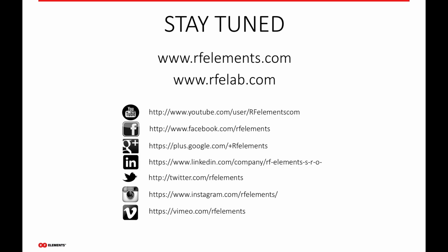Okay, thank you. Another question that just came in is, what makes horns better? Is it the waveguide? Yeah, it's everything, right? And there's no just horn antenna, right? I mean, horn is a very, very generic term to describe what we've created, and what we've created is totally different. There's many types of horn form factors. Our horn antennas are made specifically, or the type of horn, the scalar horn, was picked and used specifically for its very clean signal.